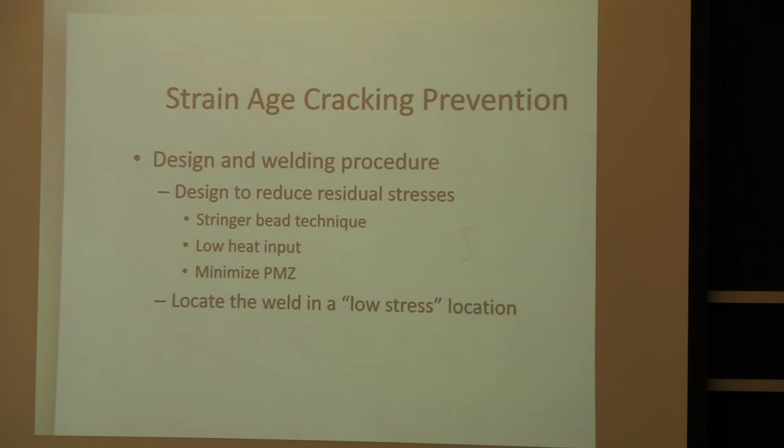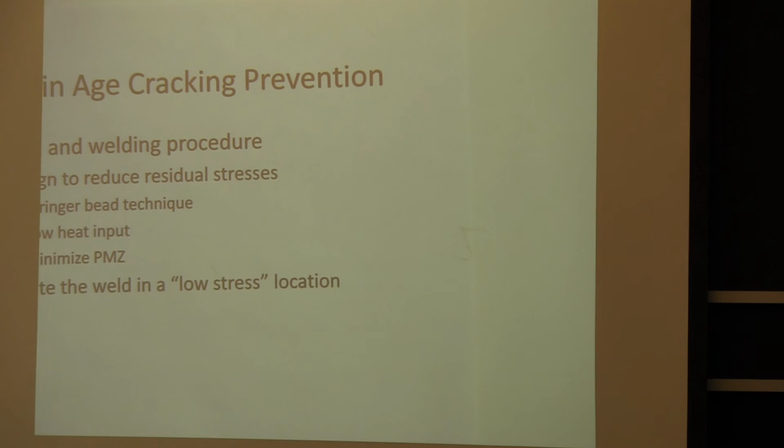You can also, as you're designing your structure that's welded, just try to put your welds in locations that will not create as much stress or be in as stressed of a state. And as you do those things, you can reduce the cracking phenomena.